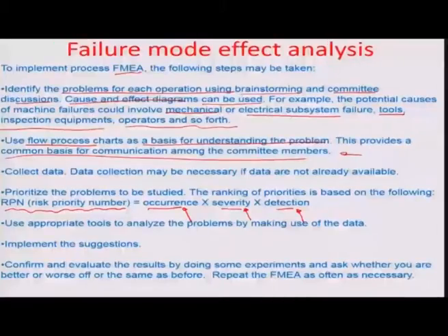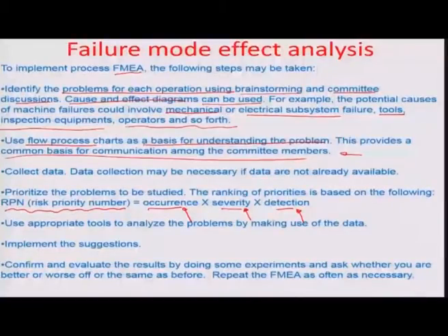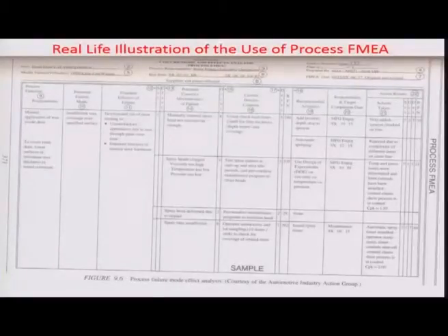So, we will try to do this again in a problem example where you will understand better what I am saying in terms of how ratings could affect by generating a number and revising the number after various countermeasures have been carried out. So, let us look at a problem example from one of the automotive companies, which talks about a failure mode related to insufficient wax coverage over a specified surface of the door inner. Okay.